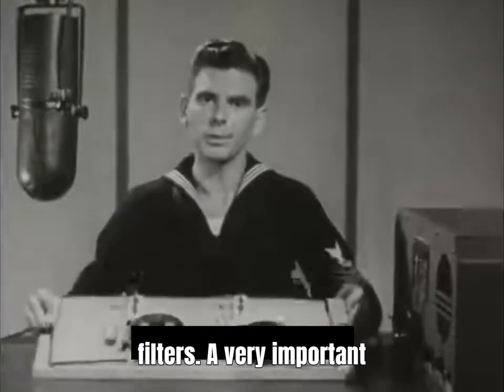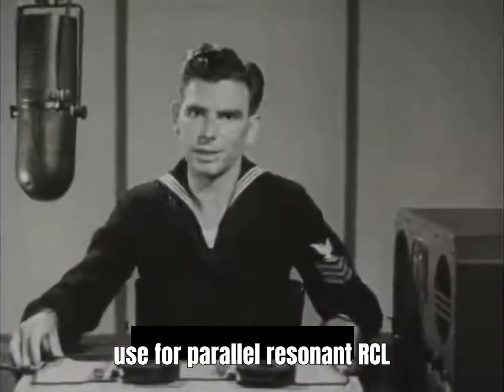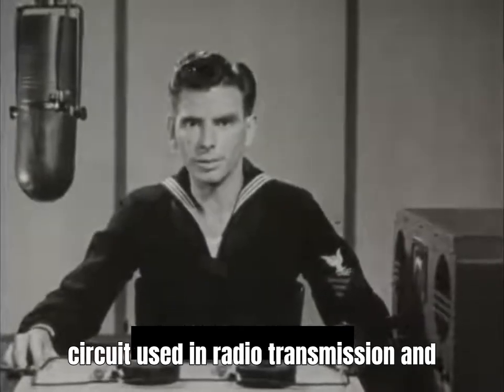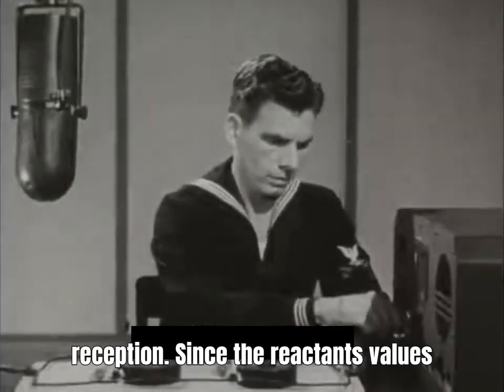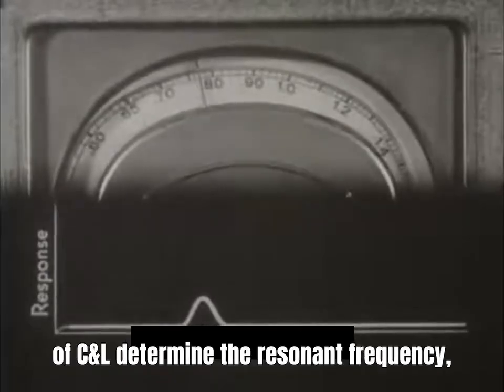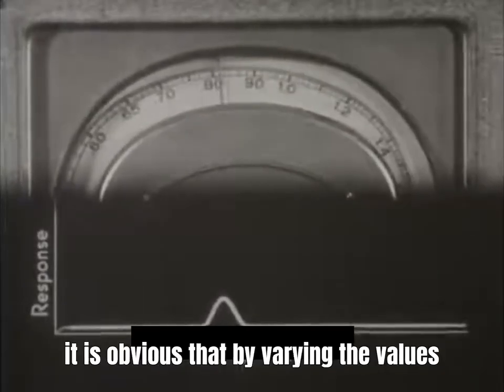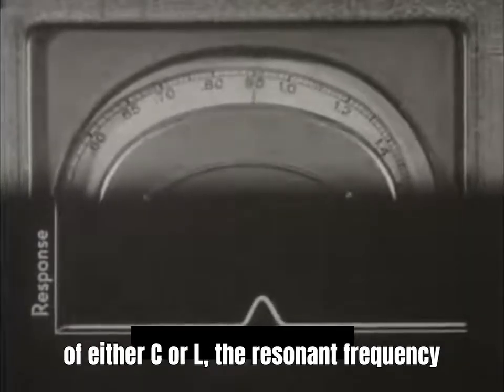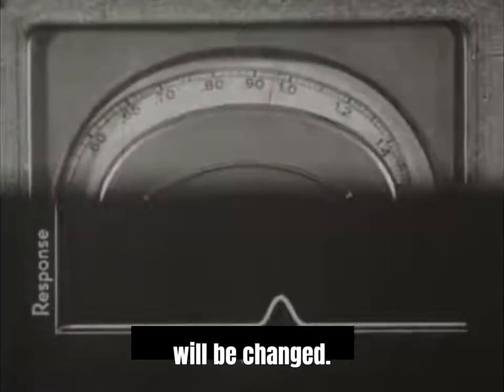A very important use for parallel resonant RCL combinations is the so-called tuned circuit used in radio transmission and reception. Since the reactance values of C and L determine the resonant frequency, it is obvious that by varying the values of either C or L, the resonant frequency will be changed.